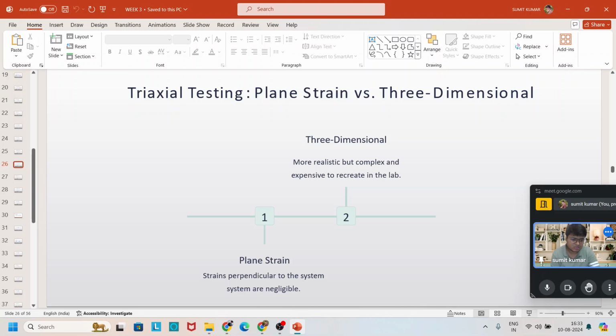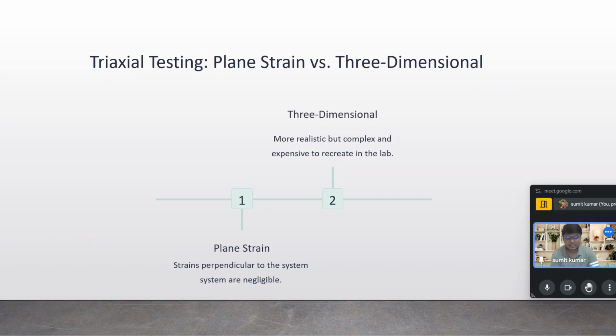Give me a minute, let me load it to full screen. Okay. Yes. So, as you remember, during the last class, I showed the triaxial apparatus presentation. Over there, you can see that we have interrelated sigma 1 and sigma 3. For your information, I will again say some points about that. We say there is the confining stage and the deviatoric stage. During the confining stage, sigma 3 is acting from all directions, and that acts with the help of the water field over there.